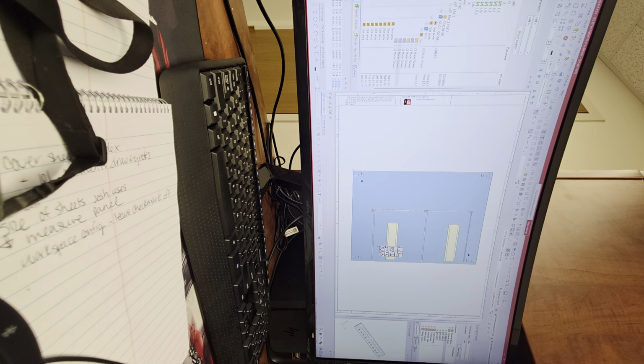Yeah, that's cool. All right, so let's just grab this GBK10 from a part number perspective, right? If you need this to be a different part number, then I would take this GBK10 in the library and just right click and say create new from this component. It's going to open up your library editor itself, but at least you have a component that is the ground bar. It just may be a different part number. Does that make sense? Yeah. And you can just say, all right, create me a new one from this, and you're done. You don't have to spend hours searching. Oh, it just did it. It did it itself.